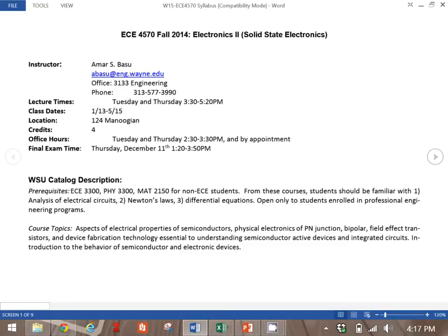When you guys sit and make your breadboards in your Circuits 1 class, right? You know that making anything more than a 2-stage amplifier is a pain in the butt, right? Because there's so many components that you have to put on there, and sometimes a component won't work, so you have to replace it. And then you get all these parasitic capacitances, parasitic things. If there's wireless signals in the room, all those little wires end up picking up the radio signals and so on. It's difficult to make very complex circuits. More than 20 or 30 circuit elements is very difficult to lay on a breadboard.